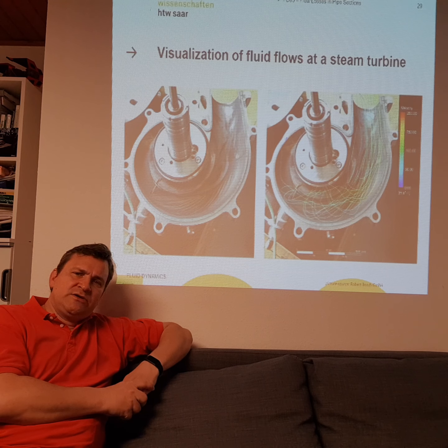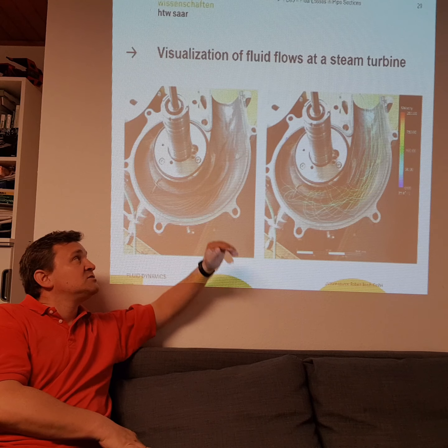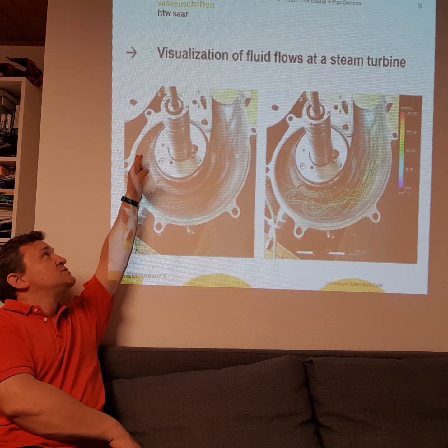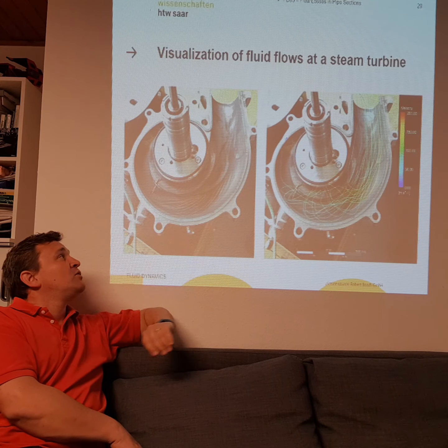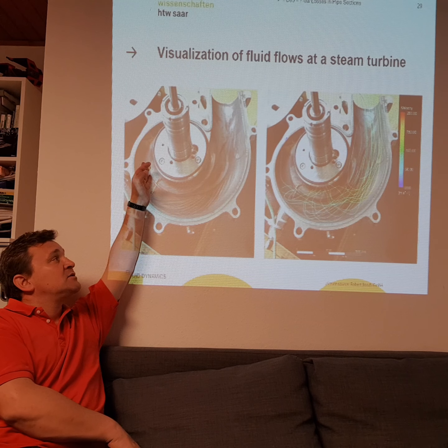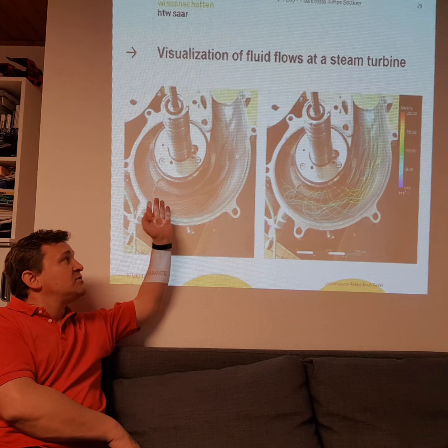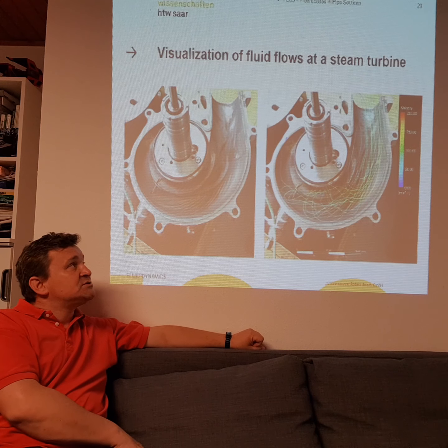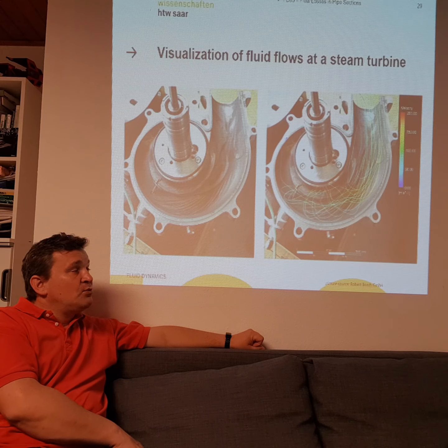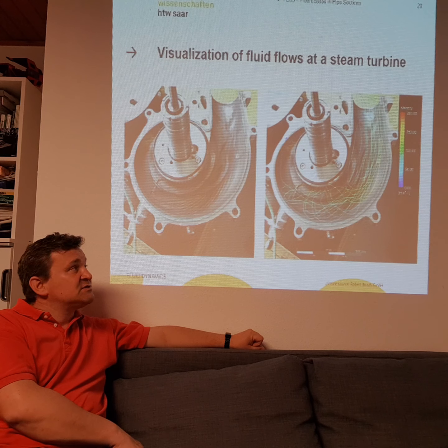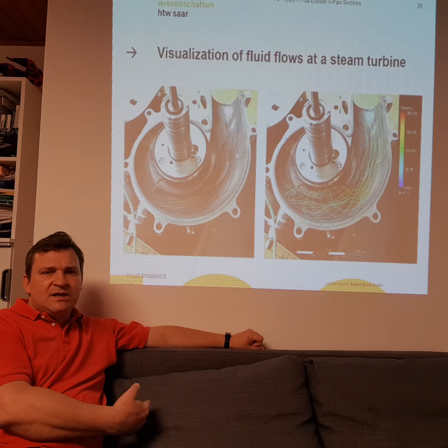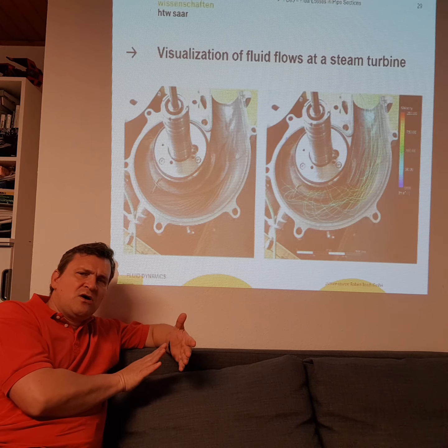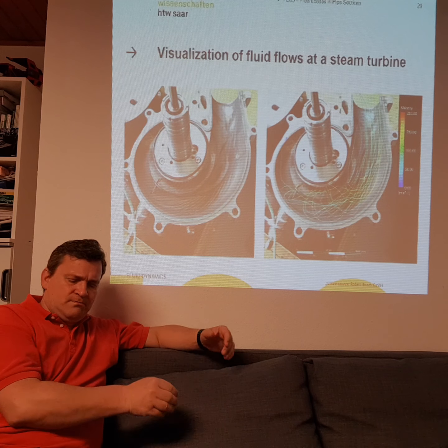On this oil layer, if you look closely at the slides, you can see really good streamlines of the fluid flow, where you had more turbulent flows and really low velocities, where you had high swirls, and a really big turbulent swirl at the axis of the snail. What I did was make a model in CFX for this snail. I made a CFD simulation and then placed it directly over the picture to visualize the flow inside the snail.